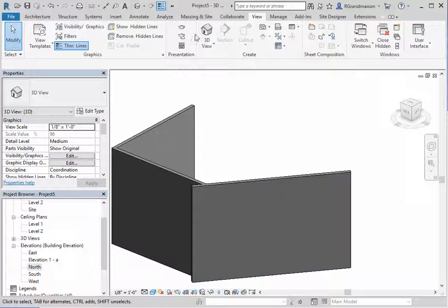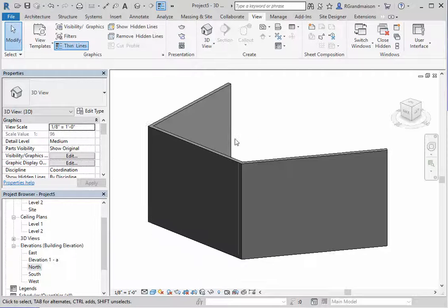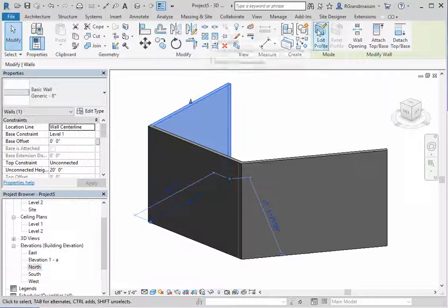So if that happens, you can just go back to the trim tool. I'll just type in the letters TR to invoke the trim tool, and I'll pick those two walls, and it cleans up the intersection properly on the model here. I hope that explains how the tool to edit profile works for you in Revit.